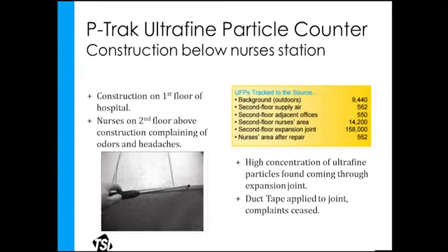What we've had good success with people doing with these is teaching them to use them as a sniffer. There really aren't metrics on what your air quality should be for particles per cc that the instrument measures. There really isn't anything established, but you sniff around and find the areas that are higher than they should be. So here's an example of a hospital.